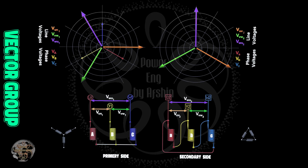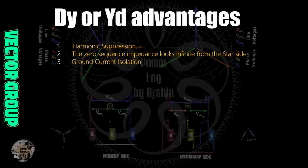Adding a delta winding eliminates most YY drawbacks. The primary advantage is harmonic suppression. Since third harmonic currents are zero sequence, they circulate inside the delta loop and do not escape to the grid. Also, the zero-sequence impedance looks infinite from the star side. Another benefit is ground current isolation.